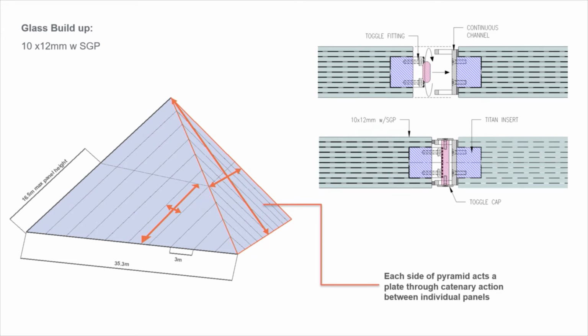So the glass panels, in this sense, drastically decrease in thickness. What we originally landed on in the early stages were about 10 sheets of 12 millimeter, which is very thick, but these are very large panels, 20 meters, and we think it could probably go down to 8 sheets of 12 mm with a bit more refinement. And for the glass panels here, there are no moment connections between them. There's just in-plane shear being resolved, and also tension and compression membrane forces.